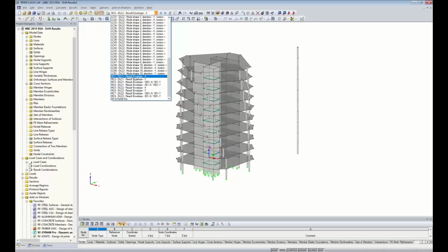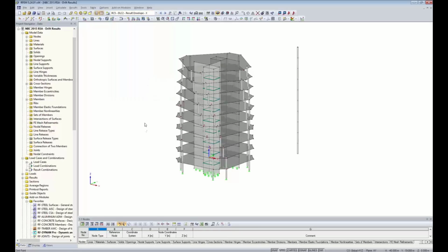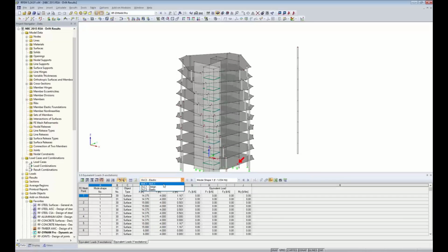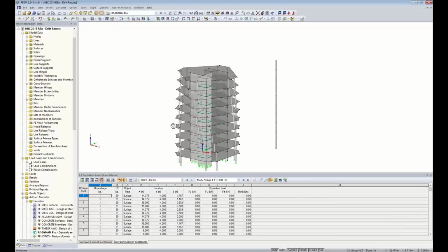And that's just simply because we have our dynamic load case 1 for our design response spectrum, and we have dynamic load case 2 for our elastic response spectrum. When we take a look at our table and we visit our table 5 here for dynamic analysis, what you'll notice within our drop-down box is we have our natural vibration case from way back when, and now we have 2 dynamic load cases here as well.